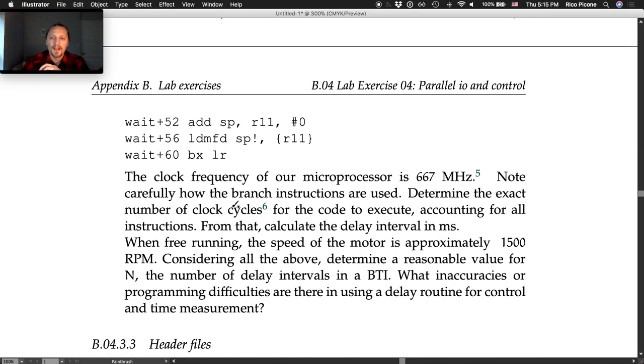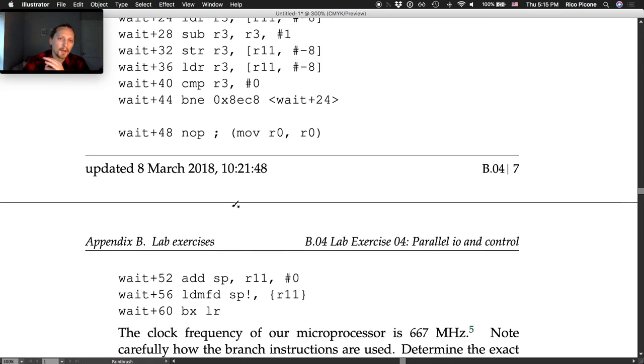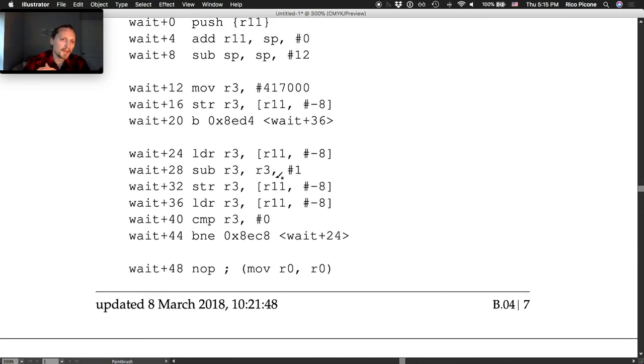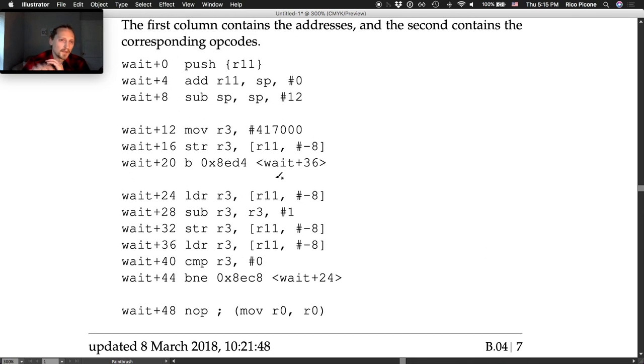So anyways, it's interesting to go through and look. Timing is difficult on these more complex processors, but we can still get pretty close, especially if we limit the number of different opcodes we use. We're not using very many exotic opcodes here, and no 64-bit pieces of data, which is another thing that throws a monkey wrench into the timing as well.